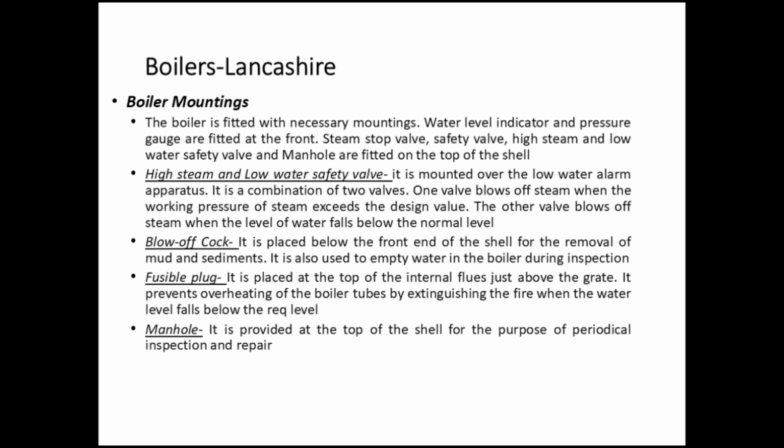High steam and low water safety valve. It is mounted over the low water alarm apparatus. It is a combination of two valves. One valve blows off steam when the working pressure of steam exceeds the design value. The other valve blows off steam when the level of water falls below the normal level.